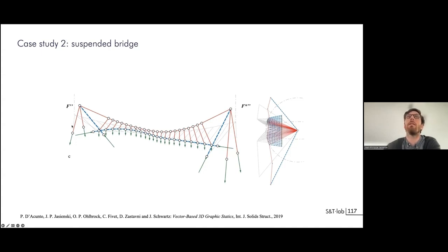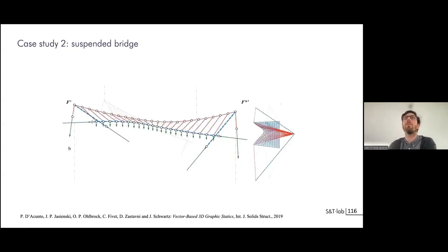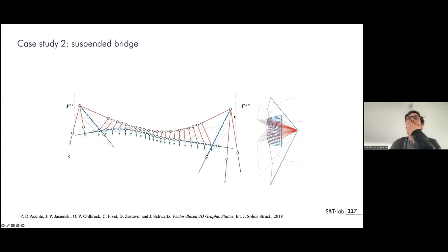And so that makes it in equilibrium for whatever load case, because this one is a kinematic structure, meaning that it's only stable for this load case. But if you have forces that push there, since this and this are in the same plane, it cannot be at equilibrium. Here we have what we would call a tripod.